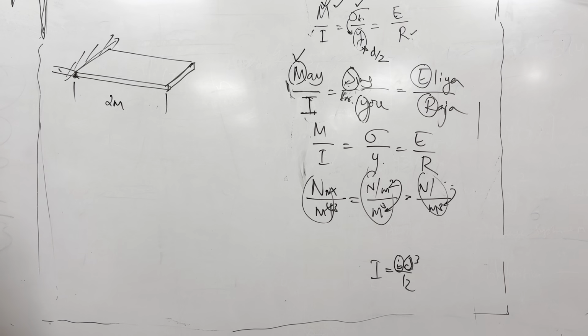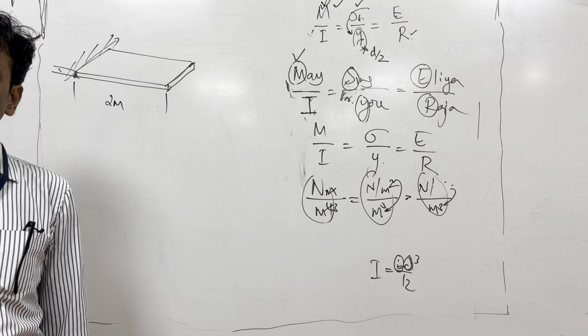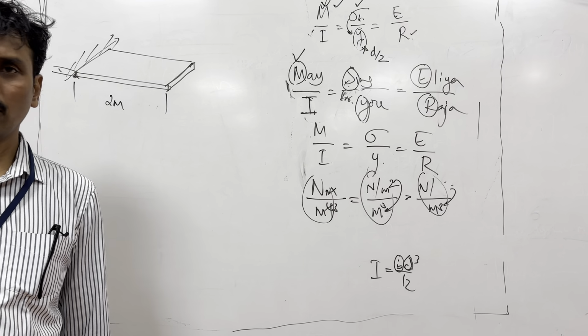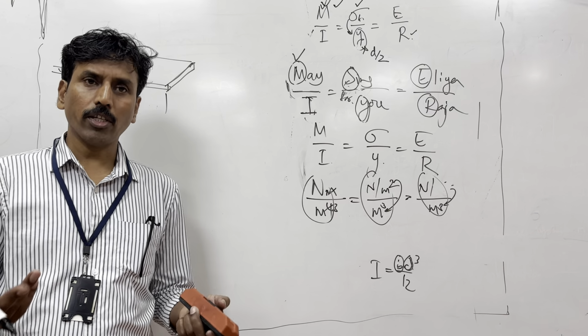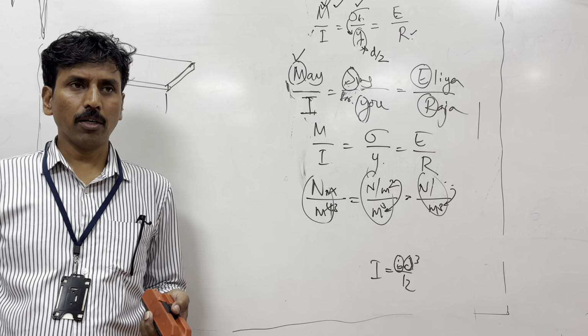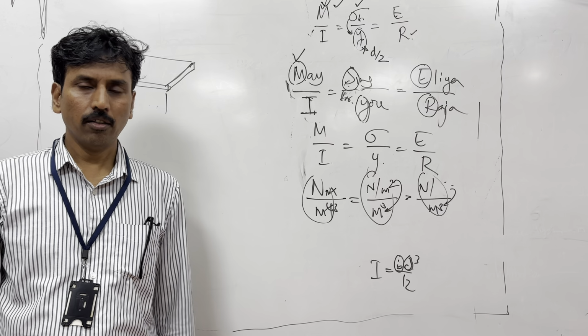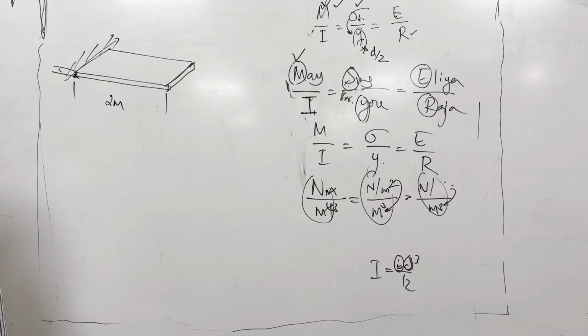Okay, guys, I think wood is a better material, and you can have even maybe glass fiber reinforced plastics or plastics. Okay, it should not be brittle, because the person may actually end up suddenly crashing down. So definitely it's not metals, because it's too heavy and it will not flex easily. It should have something to flex easily.